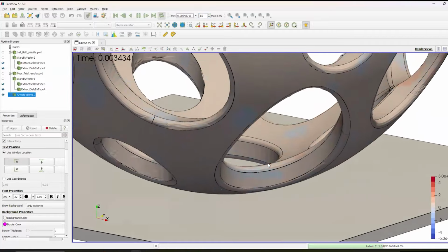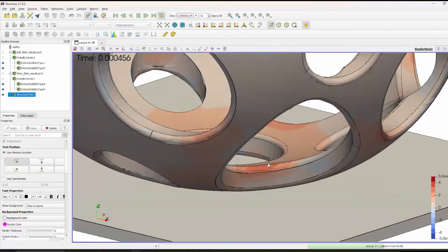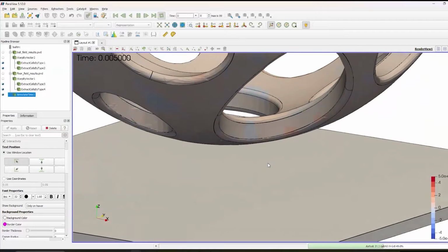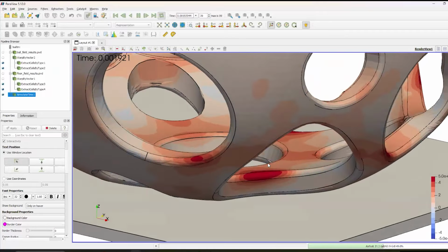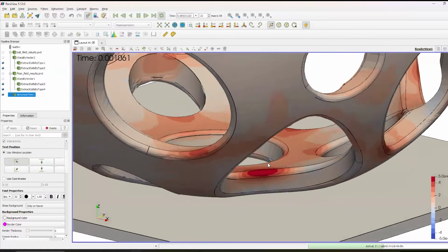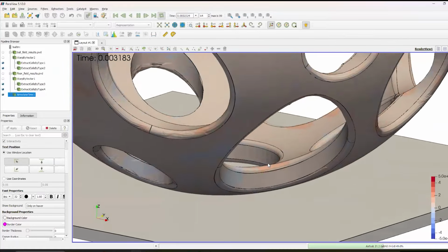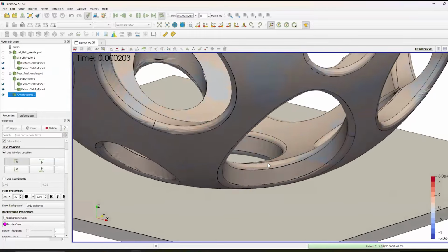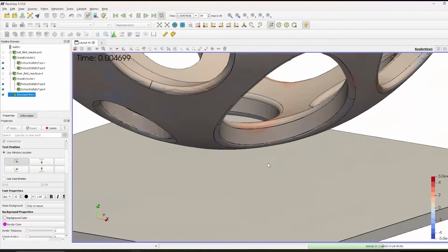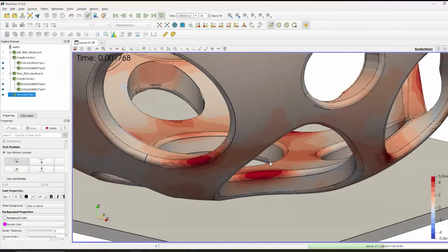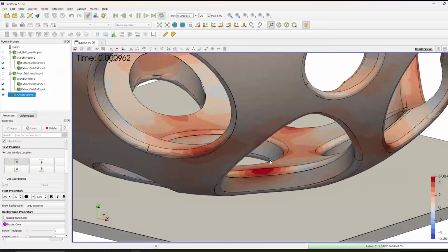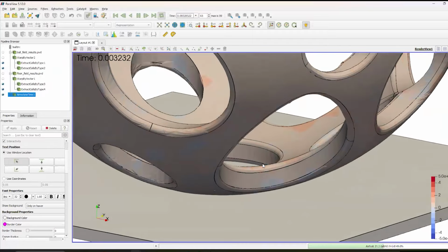And that's where if I had removed those fillets, then I'm going to have to do more hand calculations on my end to approximate what the maximum stresses there would have been, and rules of thumb for that. Maybe even make a breakout model just to simplify the problem. But without having to defeature, I don't have to worry about those modeling assumptions that have come into play.